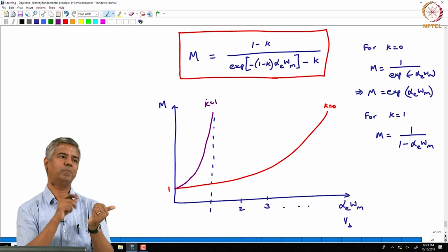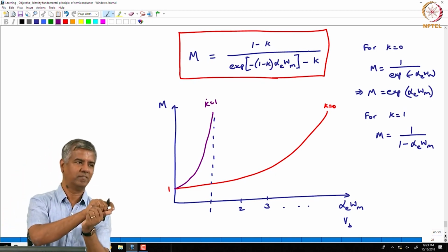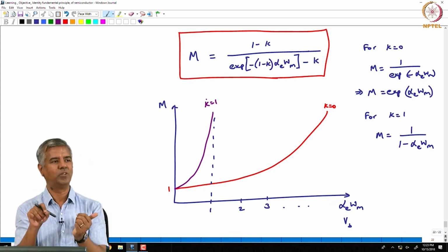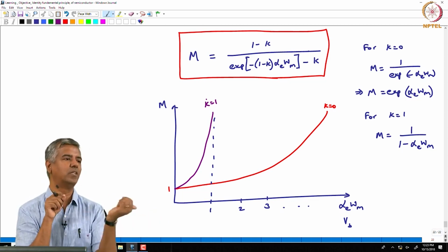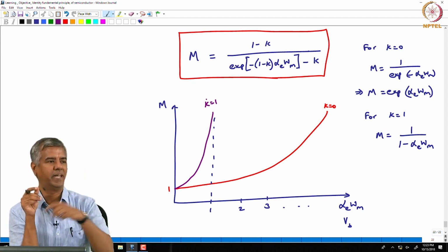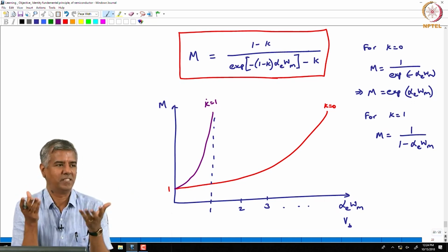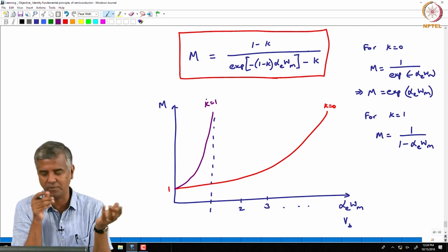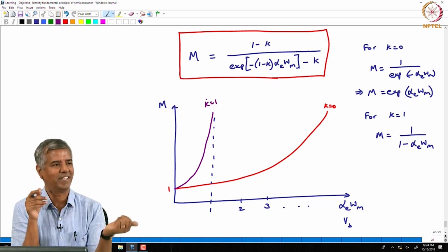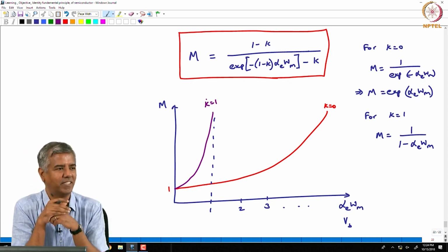How does the hole propagate? Because the neighboring electron will occupy this hole. So, the hole will go this way, and then that neighboring electron from there is going to come here, and so it is as if the hole is propagating. But in the process of electron jumping over, it can actually ionize. And so, you say holes are generating avalanche as well. So, that is a very good question, but whenever there is a hole, there is also transport of an electron that is happening. So, that is actually as if the hole is going that way.